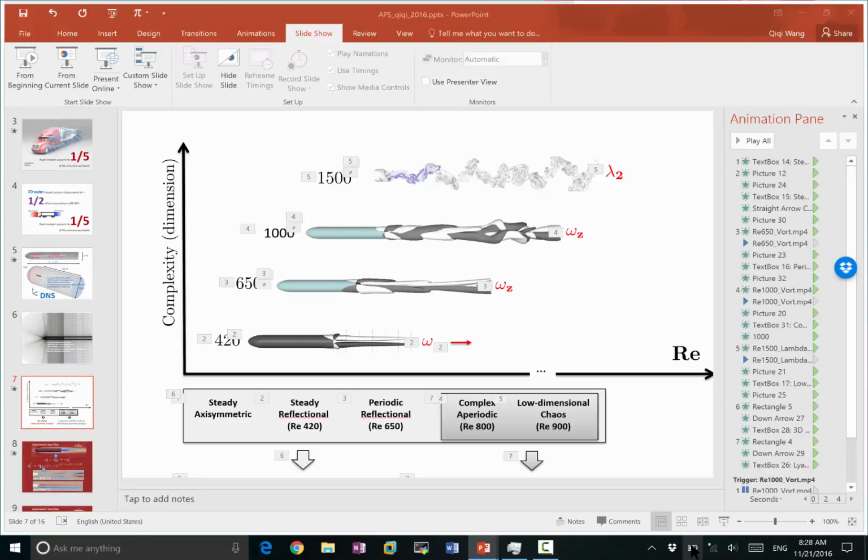So now we study this problem in a range of Reynolds numbers. As you can expect, when you have a very low Reynolds number, it starts with a completely axisymmetric flow. When the Reynolds number goes a little bit higher, the symmetry breaks. Although you still see a symmetric flow over there, if you look at it sideways, it's no longer axisymmetric at that Reynolds number.